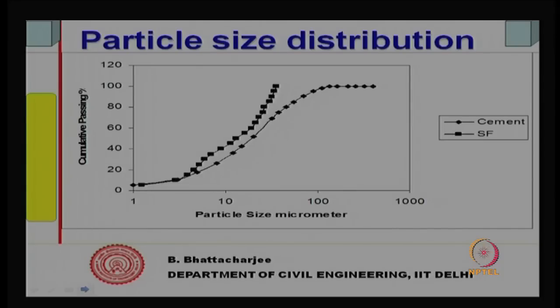Particle size distribution of cement is important. In other words, fineness of the cement is important. Finer the cement, it will react fast, but at the same time it will require more water for wetting or standard consistency. Finer cement can gain strength early. Now, how do you measure particle size and its distribution of cement?